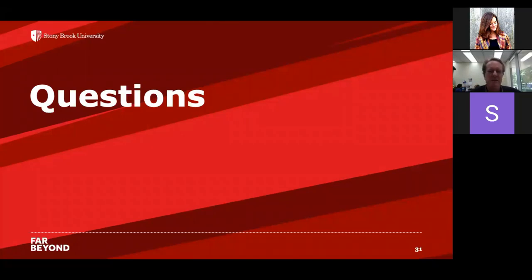Maybe the best, longest record is up at Waterloo. Robertson et al. published a paper in '95 where they put in a similar wood chip biofilter that was receiving septic effluent. Fifteen years later, they published a paper, in 2010, and it was still denitrifying. And now they're still going, and it's still denitrifying. So that's 25 years already, and it's still going strong.